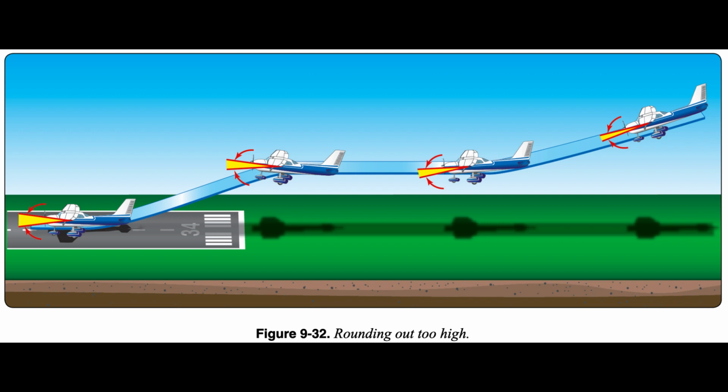When the proper landing attitude is attained, the airplane is approaching a stall because the airspeed is decreasing and the critical AOA is being approached, even though the pitch attitude is no longer being increased. Figure 9-32. Although back elevator pressure may be relaxed slightly, the nose should not be lowered to make the airplane descend when fairly close to the runway unless some power is added momentarily. The momentary decrease in lift that results from lowering the nose and decreasing the AOA might cause the airplane to contact the ground with the nose wheel first and may result in nose gear damage or collapse. It is recommended that a go-around be executed any time it appears the nose needs to be lowered significantly or that the landing is in any other way uncertain.